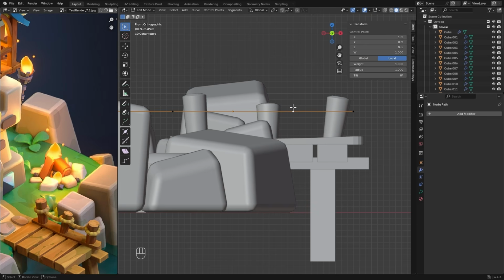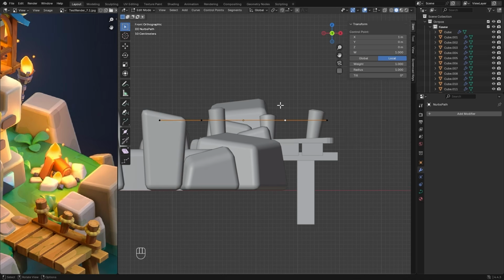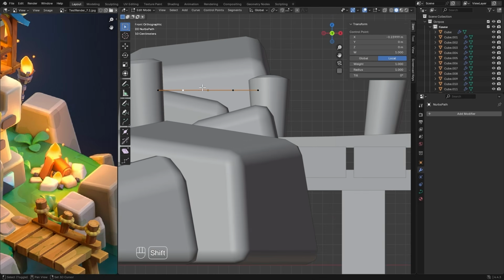Here, we can drag the points, thereby changing the curve's shape. Now I'll select all points by pressing A and scale this curve down, S, and I shrink it. We won't need these 2 points, so I'll select them, press X to dissolve vertices. Let's drop the middle point lower to create a bend like this. And we'll raise this one higher.